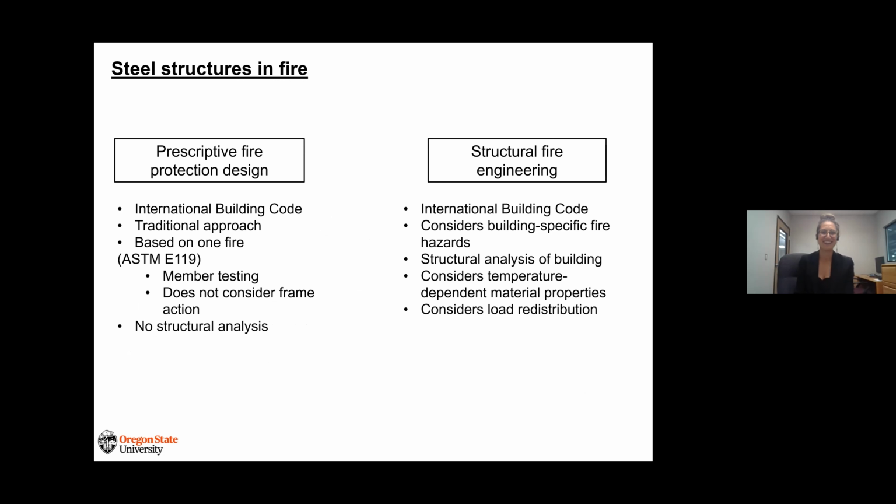For those practicing engineers in the audience, you're very familiar with the prescriptive fire protection design methods through the International Building Code. This is the traditional approach. It is very prescriptive, where you just look up what your required hourly rating is, and there's no structural analysis. You really don't have to do any calculations to determine that. That is not really where the research falls.